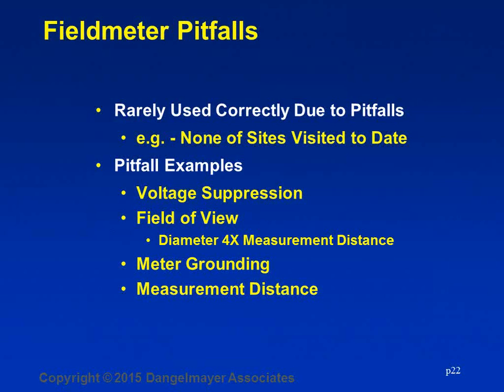So if you're measuring something on the bench and part of it is the workbench itself, the ground measurement of the bench, or the 0 voltage level, will lower the reading artificially. Often people measure without grounding the meter, or they use the incorrect measurement distances. And these are a few of many that result in readings that are not accurate.